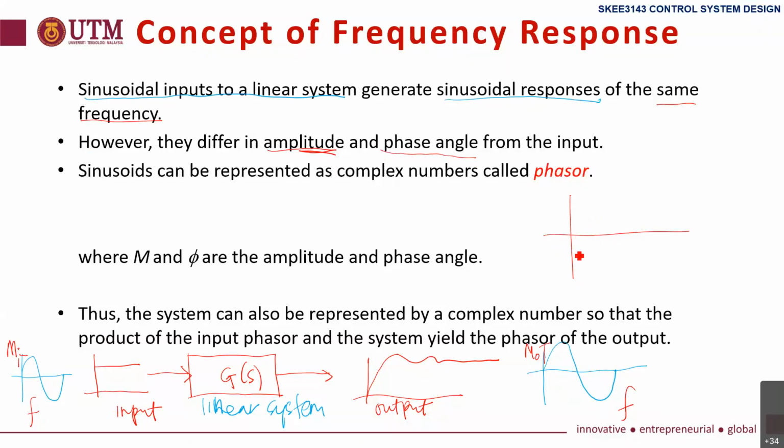So the phase angle between these two will also be different. Again, if the input is sinusoidal, the output will also be sinusoidal with the same frequency, but they differ in amplitude and phase angle. That is the first basic concept of frequency response.